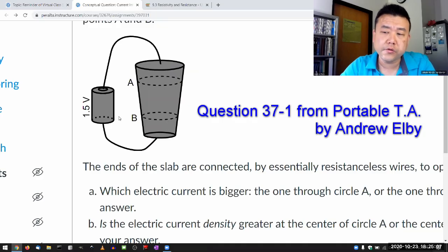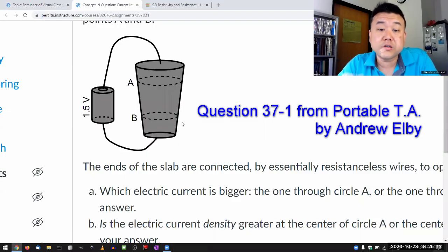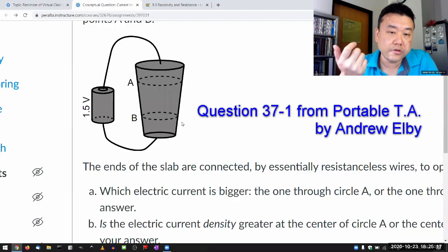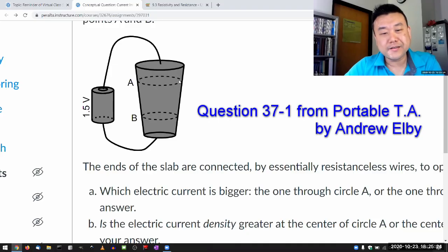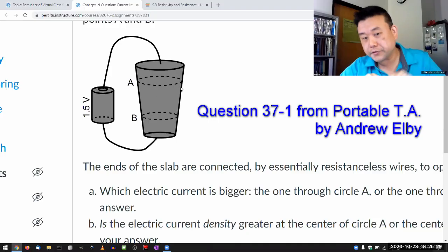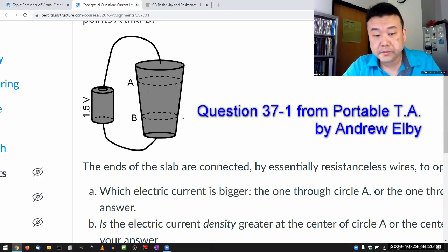And if you've gone the route of thinking of charges moving like cars moving on a road, then using that wrong analogy to ground your intuition, you would wrongly go into thinking that in this wider part, current flows more easily, so more current flows. And in this narrower part, current flows less easily, so current is less there. That's an easy, intuitive, conceptual mistake to make.